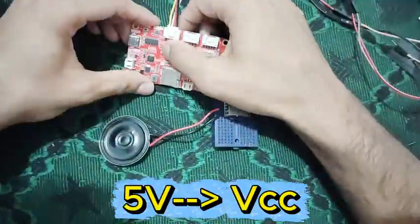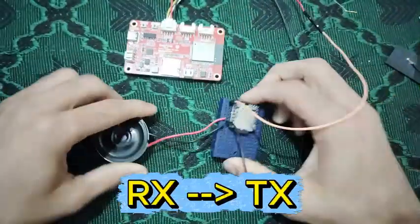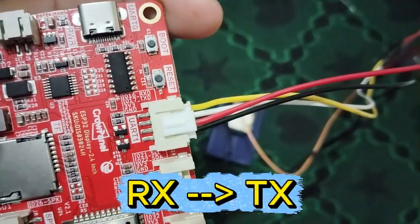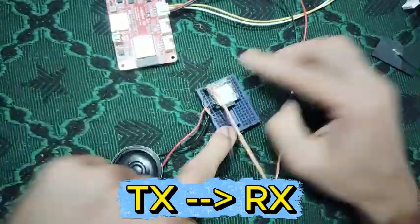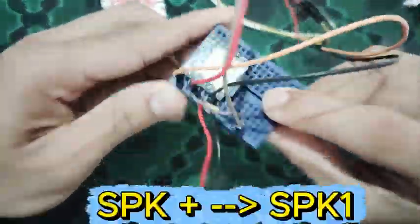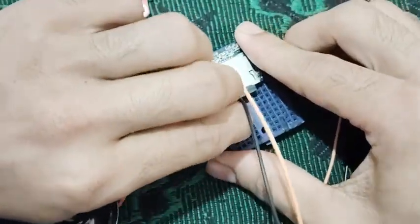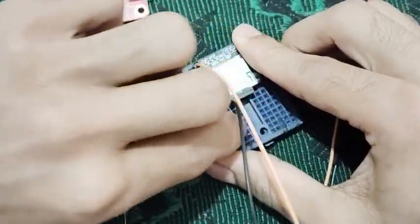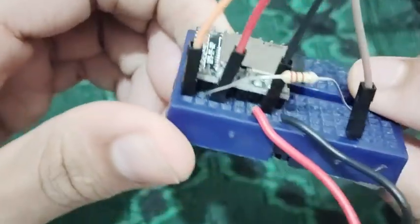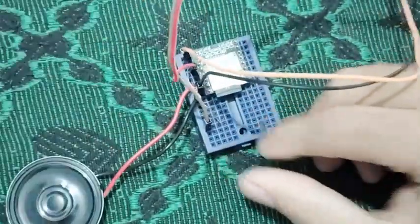Connect the DFPlayer's VCC to 5 volts, the ground to the ground, DFPlayer's RX to the ESP32's TX pin, which is GPIO 17 here, and DFPlayer's TX pin to the ESP32's RX pin, which is GPIO 16 here, and the speaker pins, positive of the speaker and minus to the minus of the speaker. It is recommended to connect a 1 kilo ohm resistor in series between the RX pin of the DFPlayer Mini and the TX pin of the controller. Initially, I got pretty noisy output, so I just hooked a resistor to it.